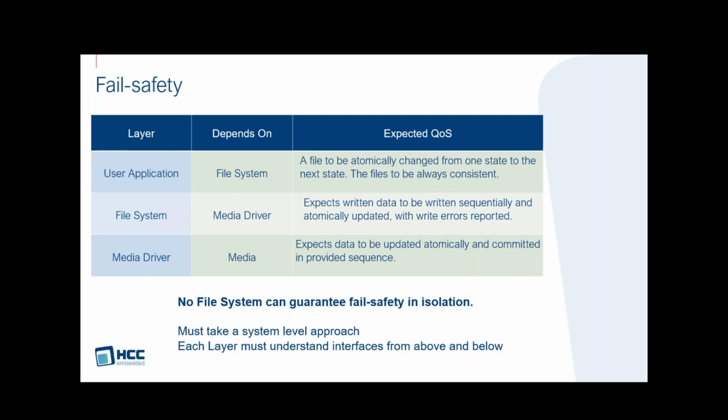To give you a concrete example of where this goes wrong, if you look at Linux systems, there are at least four file systems that claim to be fail-safe. And lots of people find that when using these file systems, they don't actually achieve fail safety. One of the problems is that in Linux systems, you often have people who develop board support packages, who write things like NAND drivers with no idea what version of Linux is going to run, or what file system is going to be interfaced to those NAND drivers.